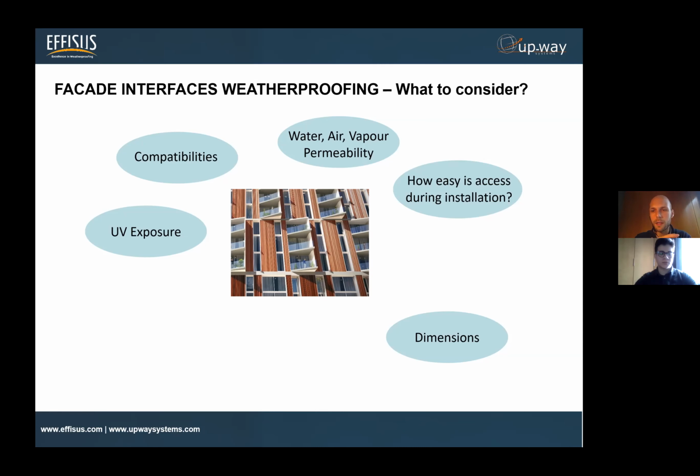Imagine that you are dealing with an interface where it's a really narrow space and you're finding it really difficult to play with the membranes, cutting, overlapping, etc. It's really important that people on site get a solution that is able to be installed in that specific condition. And we cannot tell ourselves that there are no such solutions, because there are, and you just need to understand the specific situation in order to get the best solution for that specific purpose.